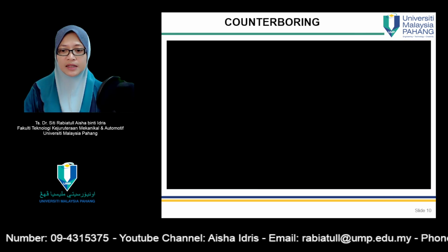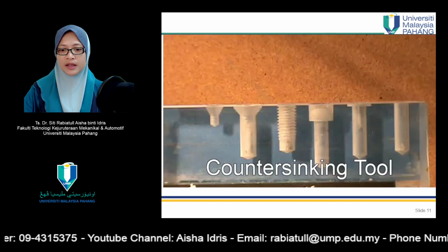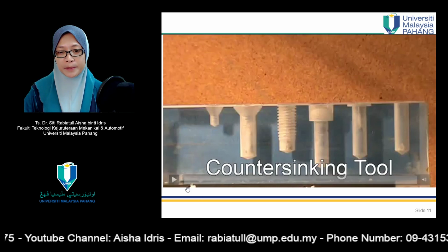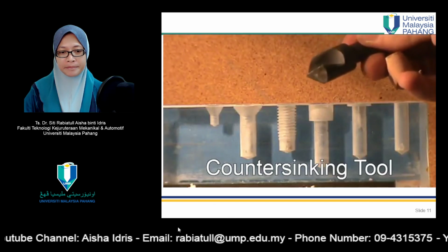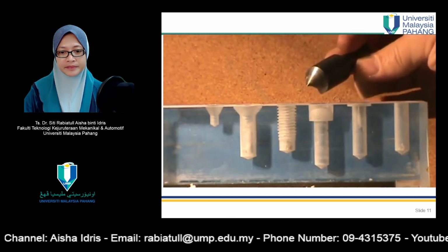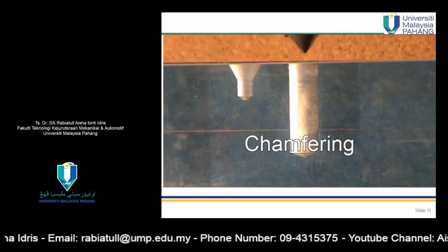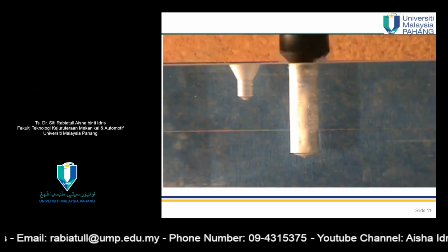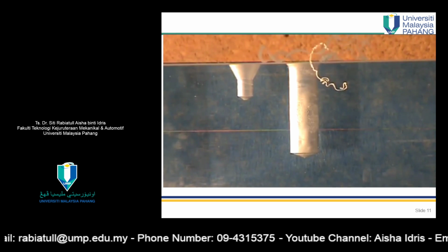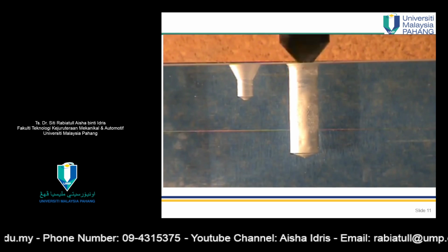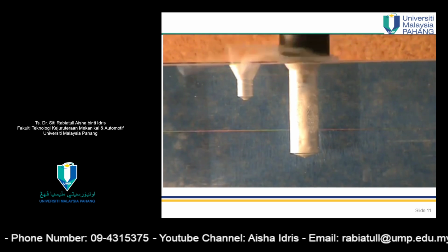So that is counterboring. And let's look at what is countersinking. Okay, this is a countersinking tool. Two different things that we can do with the countersinking tool. First one is chamfering. Chamfering is just going in and breaking that edge around the top. If we go deeper with the tool, the operation is called countersinking. We'll use this for a flathead screw.